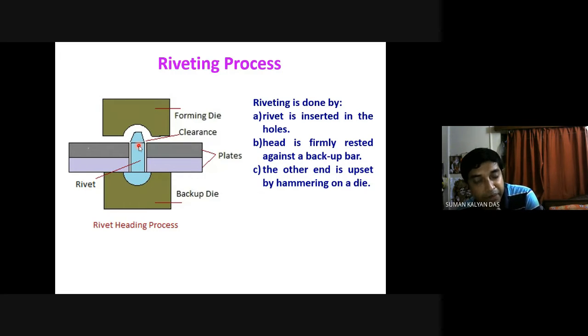So you need to make a leak proof arrangement such that the hole can be covered. For that, those vendors used to have aluminum rivets. They would put the rivet at that hole and use the same process that I am talking about right now. However, they did not use a second plate, because their intention was not to join two plates, rather to cover the hole.